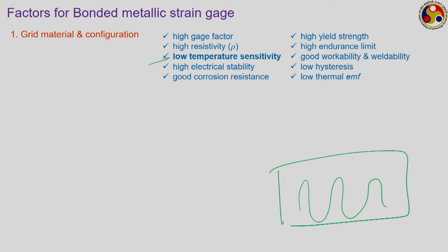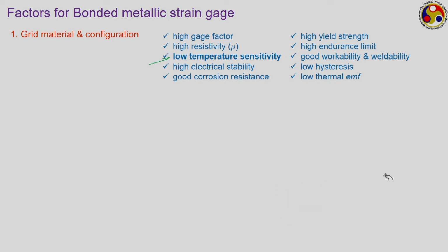Now, if the temperature increases, then the bonding between the wires and the corresponding backing material keeps on changing; that becomes weaker, thereby producing an additional strain on the resistor element. Now, your sensor generally is not able to distinguish this thermal strain from the imposed strain, thereby putting an additional factor in the final output.